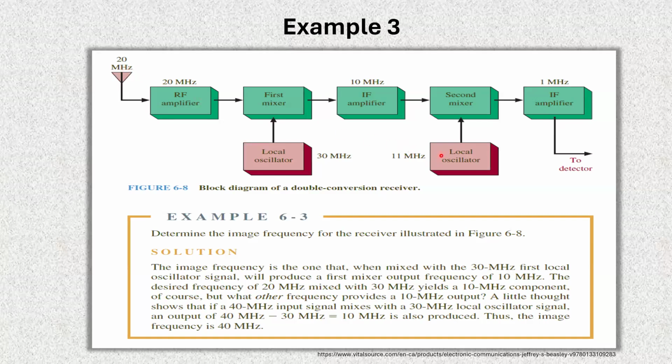We have two superheterodynes, one after the other. First, we bring it down a little bit, and then we bring it down even more, and that's what we're working with. Whereas if we just did one, some of the rejection of certain frequencies that are adjacent would be more difficult.